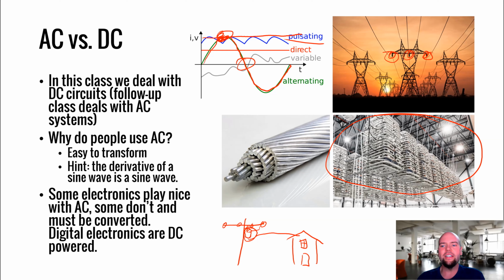Getting back to it though, I've spent a long time, I wandered on this. But there's not some fundamental principle of AC versus DC that says DC can't travel as far as AC. What people are talking about is it's difficult and expensive to transform DC. And as a result, typically when you have DC systems, you're not able to just take a high voltage and low current and then transform it to a low voltage high current when you get to where you need it. You can't do that very easily. And so it is the ease of transforming that makes AC so popular. It's super easy to transform.